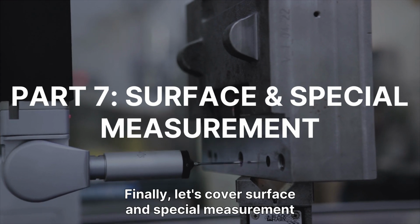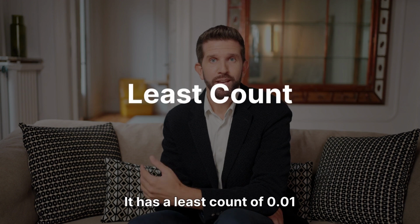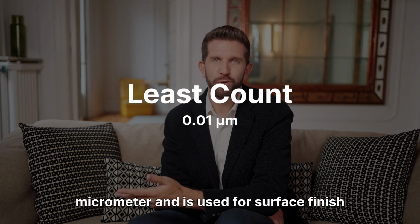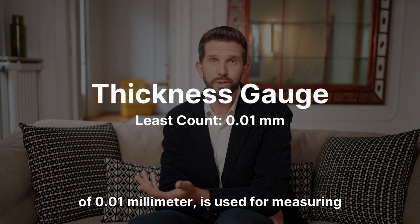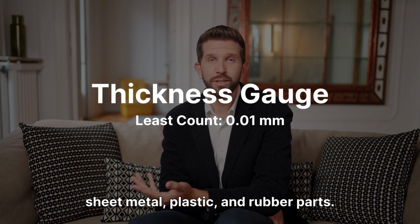Finally, let's cover surface and special measurement tools. The surface roughness tester. It has a least count of 0.01 micrometer and is used for surface finish measurement. The thickness gauge, with a least count of 0.01 millimeter, is used for measuring sheet metal, plastic, and rubber parts.